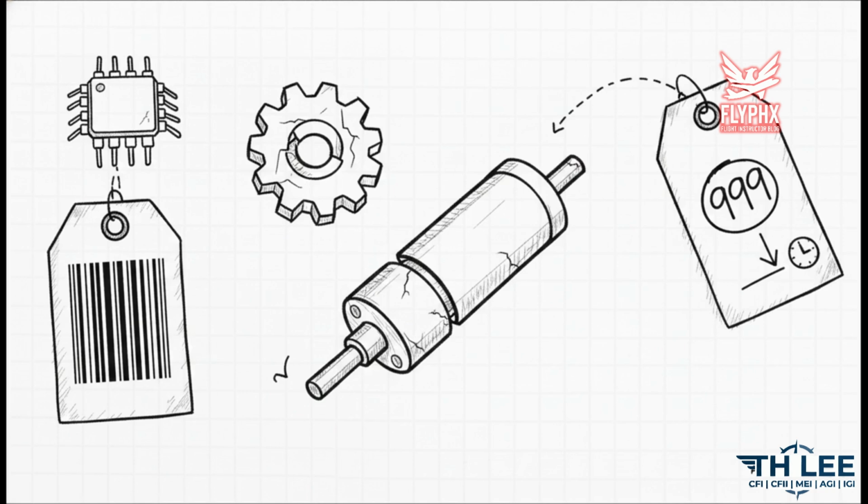And for life-limited parts, if they are physically too small or if engraving them would compromise their structural integrity, the design approval holder has to provide alternate marking instructions or attach the vital info directly to the container.